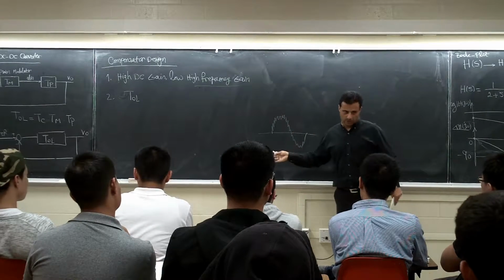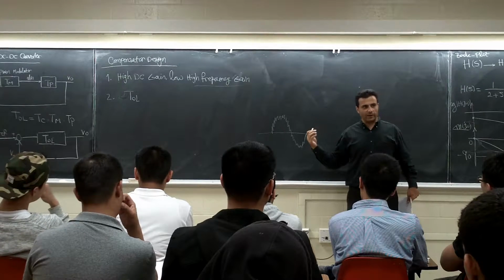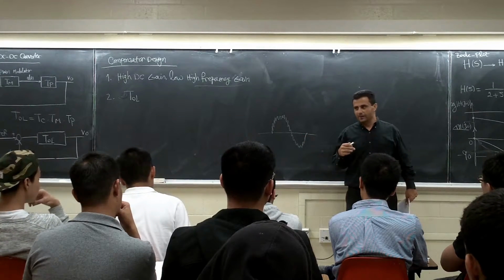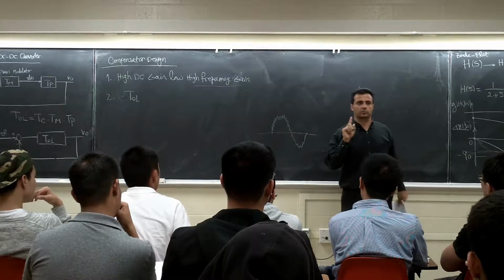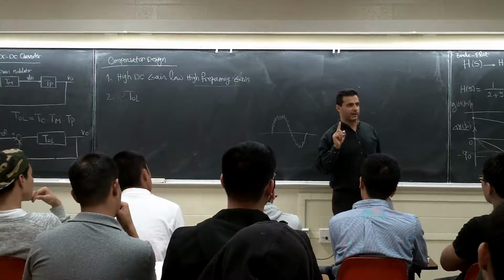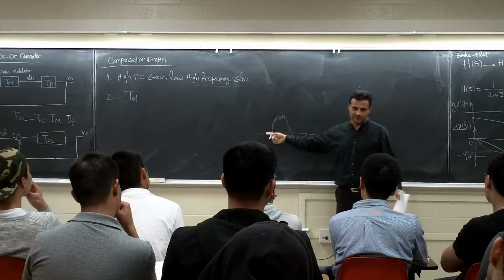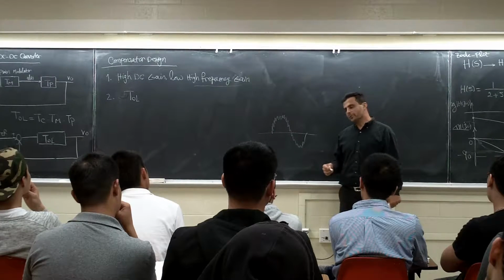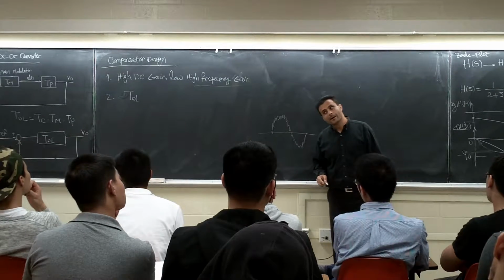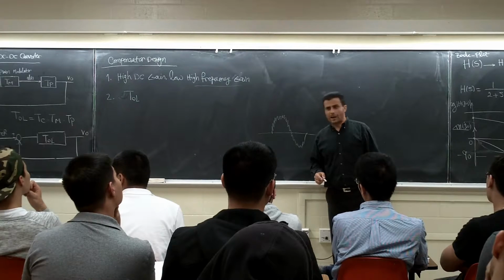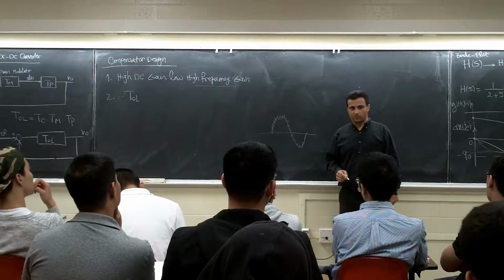I need to sense the current and bring it to my DSP. Usually I filter this current. When I filter this ripple, based on what corner frequency I'm selecting, I'm going to clean up this waveform. That's the name, filter. It's going to clean up this signal. What's the problem with this filter? It must have an effect on the original signal. So I can define the gain to make sure we get the right one. There's a bigger effect.